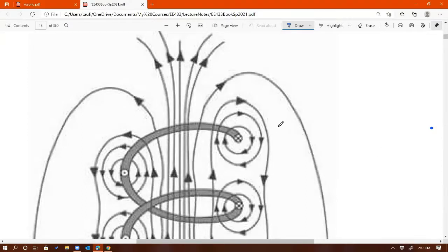Still good. So if I zoom in right there, that X means that current is into the page. Imagine that current is into the page, and by using the right-hand rule, the flux around it would be going clockwise. Yes, going clockwise. Now, two things are interesting to me here. The first one is that if I look at the bottom side of this wire, this area right here, I'm going to erase that now. Focus on that area.